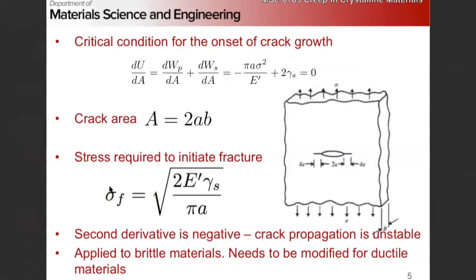So physically, that means this is only going to work for brittle materials. If you have ductile materials like a metal, we need to make adjustments to the basic Griffith analysis.